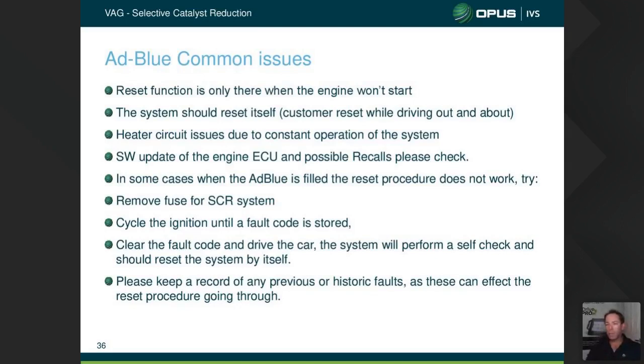But you need to fill it up with AdBlue. If you just reset it, the car starts and runs, guess what? Another 5 starts later, it's going to shut down again. So once it's full and it's been reset, the system should reset itself.